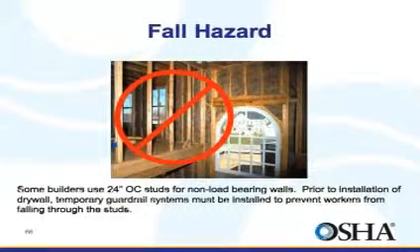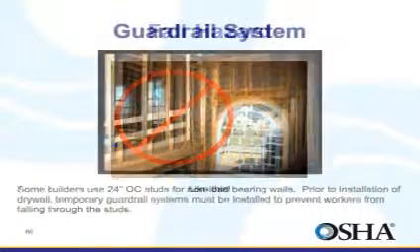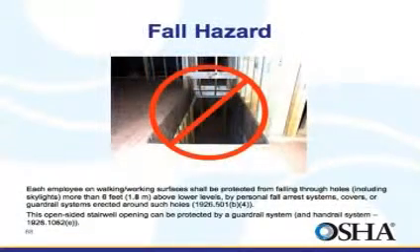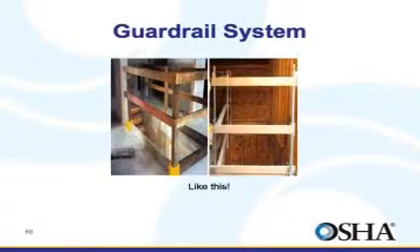Falling from roofs is not the only area where fatalities have occurred. Open sides like this must be protected. Like this. And this open-sided stairwell opening must be protected. Like this.